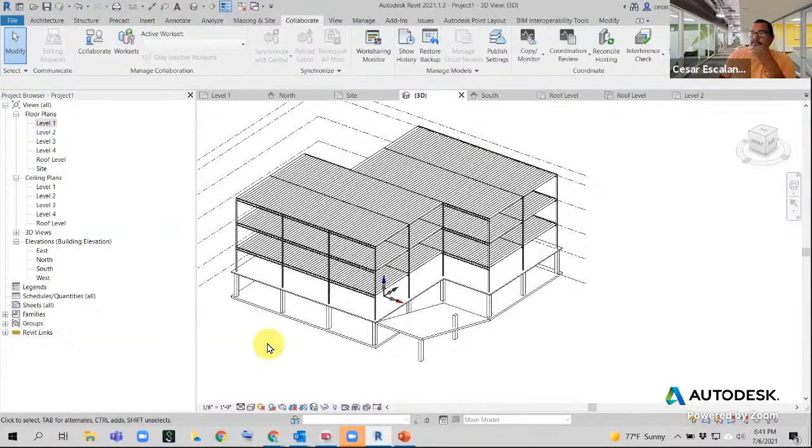So bring things back and forth between links when needed. Again, only when it's justified. Sometimes you don't want to have redundant information, and certainly you don't want to confuse consultants by having two elements in two different locations. Floors sometimes live in two different models.